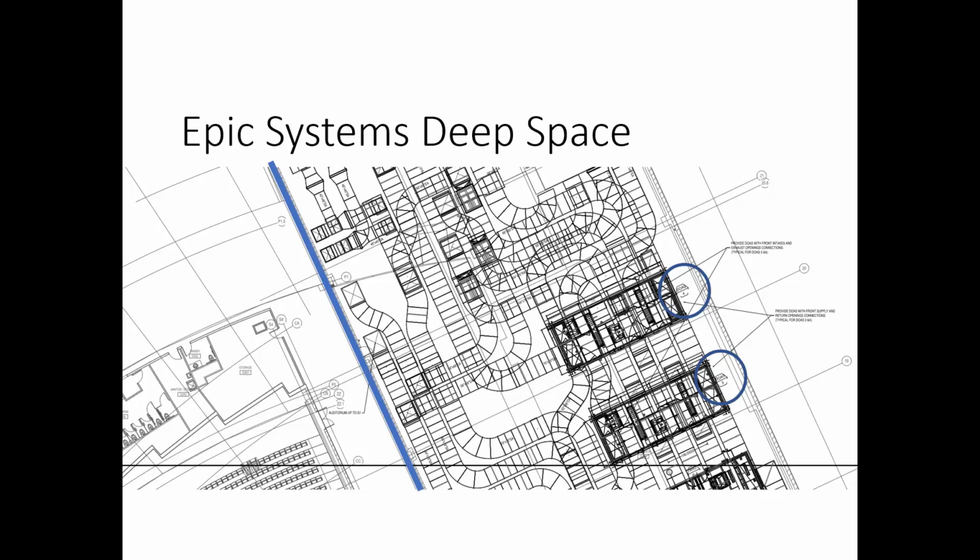But an auditorium is different because you have so many people packed in, just tight together. And the latent and sensible heat loads are different for that. So it's different than what a packaged unit is typically designed for. So if you instead supplemented it with dedicated outdoor air systems to get that fresh air and the circulation in without having to oversize the packaged units, you not only cut down on the noise, because when you oversize those units,